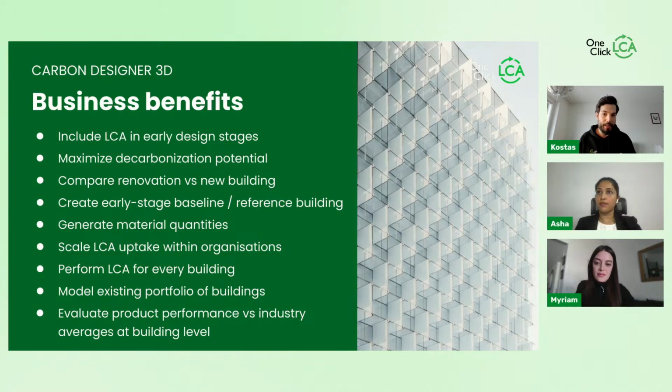And last, what can be interesting also for manufacturers is that with the Carbon Designer, you create a full building LCA where you can see the impacts, how the impact changes if you make choices of different materials and different construction solutions. So theoretically, one can generate a reference building and generate a customized building that uses the material of a specific manufacturer and get a quick comparison at building level. And all this, in short, helps you make informed decisions. So if we can move to the next slide.